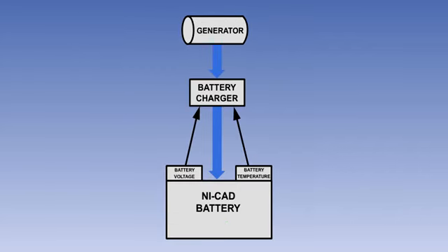With Nickel-Cadmium batteries, which are susceptible to thermal runaway, a dedicated battery charger which monitors battery temperature and voltage is used. Some Nickel-Cadmium battery charging systems use a method known as pulse charging. In this type of system, the battery charger delivers short pulses of charging current.